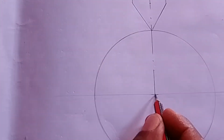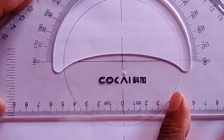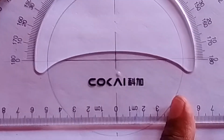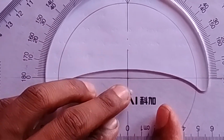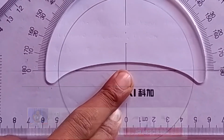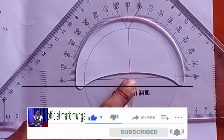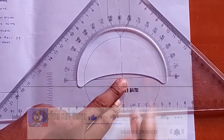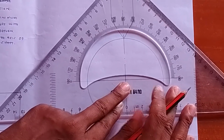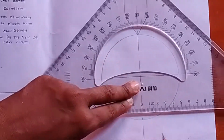So from this point here, this is where you need your protractor. You need your protractor at this particular juncture. So from this juncture, you put your protractor there from the center line of the radius. After you put it at that point, the very next thing that you have to do, when this line has aligned itself with the 90 degrees, now you want to measure. This is 360 degrees. So it is this motion that we were drawing in the cam displacement.